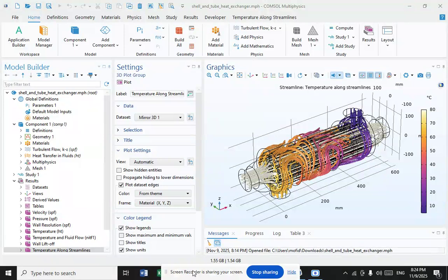Counterflow, where hot and cold fluids enter opposite sides of the heat exchanger, flow in opposite directions, and exit at opposite ends. This configuration is preferable when the objective is to maximize heat transfer between the fluids, as it creates a larger temperature differential when used under otherwise similar conditions. The simulation that you can see here above illustrates the parallel and counterflow directions of the fluid exchanger.